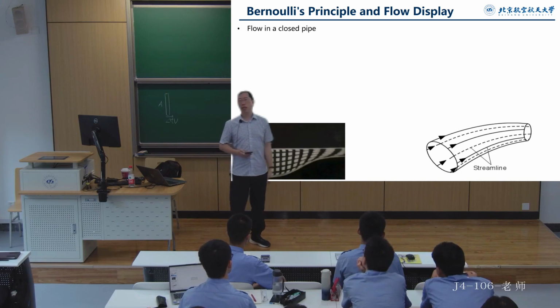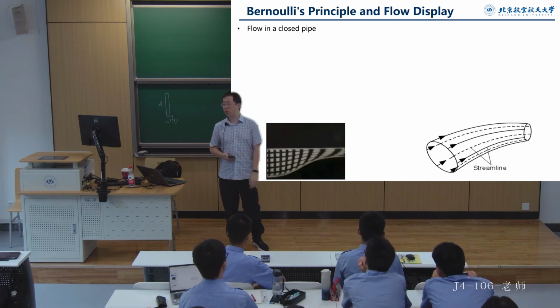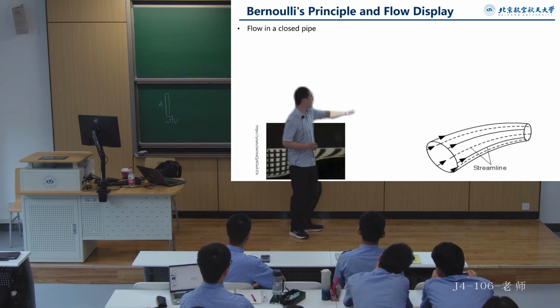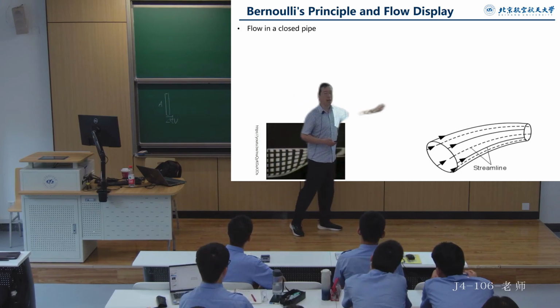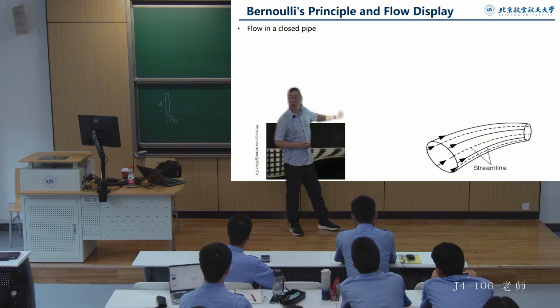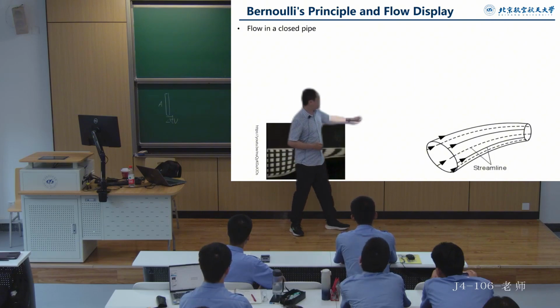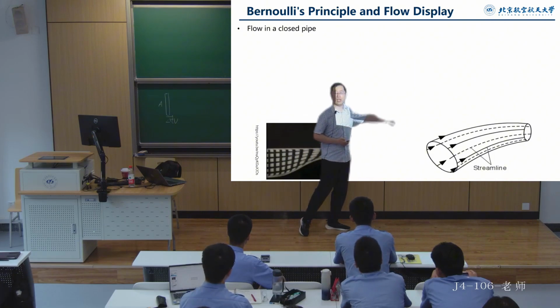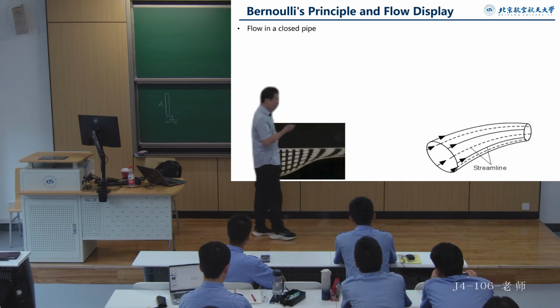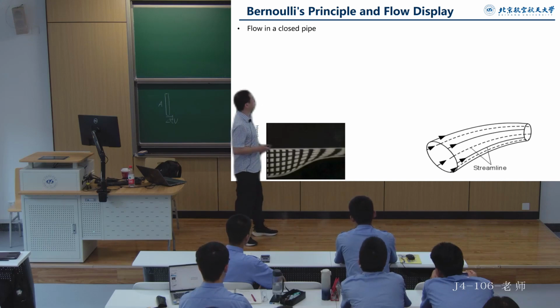In the entire flow tube, they have a conservation relationship, correct? So can we further understand how the pressure changes at these two positions? In the wider area, the pressure should be relatively larger, right? In narrower areas, the flow rate is fast, so the pressure will be relatively lower. This describes the continuous flow situation within the pipeline.